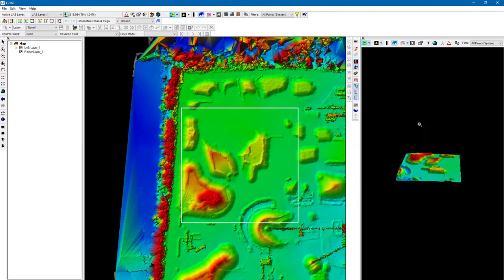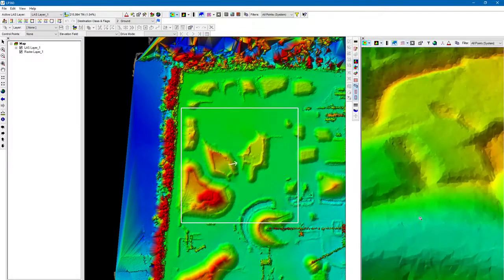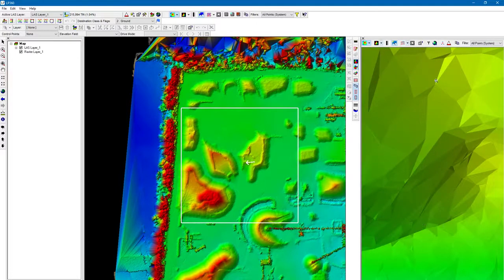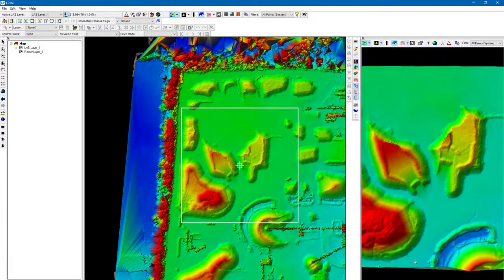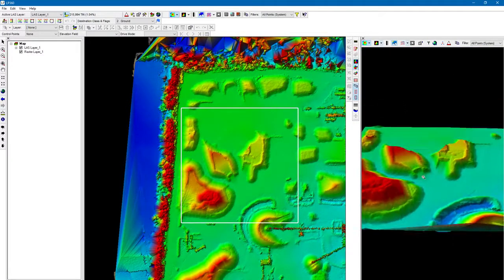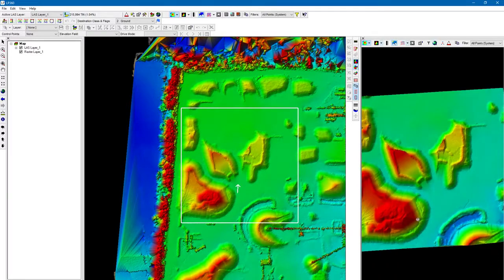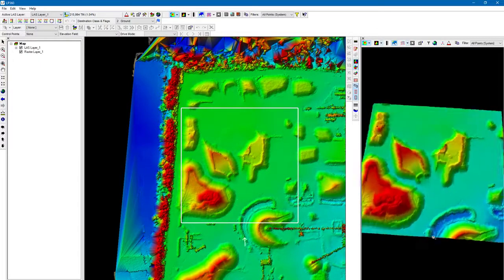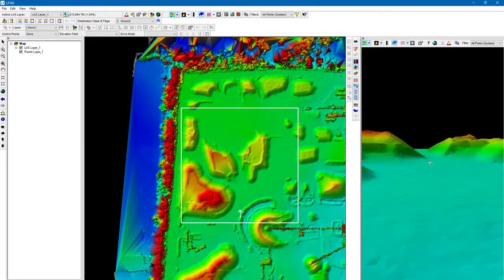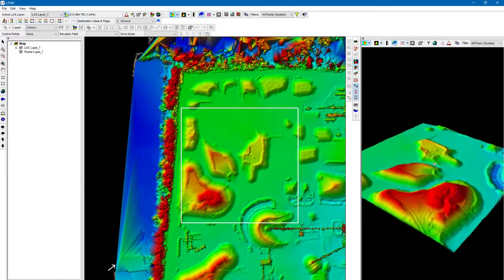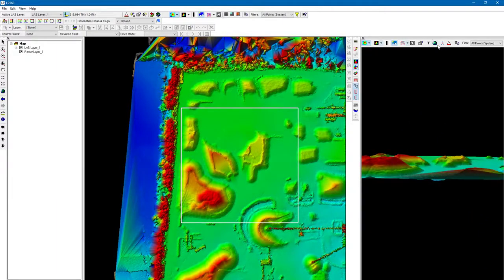Let's say we've got this view into some kind of funky spot underneath the stockpile or something like that. I want to get back to just a top-down view to start over. Just simply hit the T button. We can have a top-down view. Fit to window. I'm just going to zoom us out. So even if I'm in a kind of a wacky view, zoomed in, if I go to fit to window, it's going to keep that same rotation view, but it's going to go ahead and zoom us out.